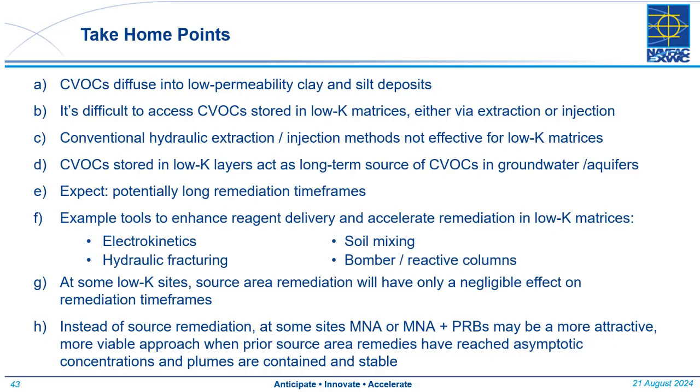However, at some low permeability sites, source area remediation is only going to have a negligible effect on remediation timeframes, and we need to think about that. At some of these low permeability sites, instead of source area remediation, we really should be looking at M&A or M&A plus permeable reactive barriers, because they can be more attractive, perhaps a more cost-effective approach than trying to go after the heart of the beast.